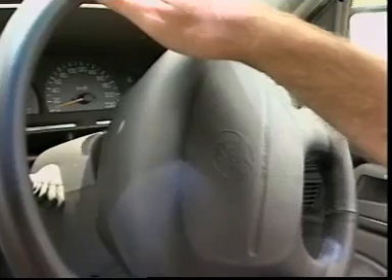The check engine lamp is a warning light on the instrument panel. It is lit up by the control unit to warn of malfunction in engine management. The check engine lamp can also indicate fault codes. They can be a series of lamp blinks or voltage pulses from the control unit. They give a number for the kind of fault that is occurring.